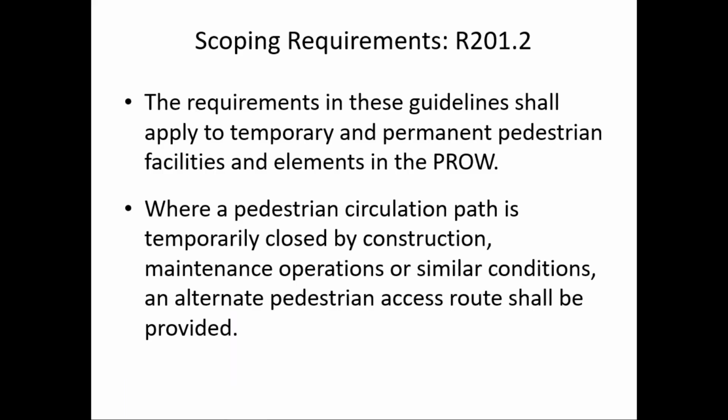Where a pedestrian circulation path is temporarily closed by construction, maintenance, operations, or similar conditions, an alternate pedestrian access route shall be provided. So there's that word shall again. So it's a requirement that when a sidewalk is temporarily closed by the various reasons mentioned here, or it could be landscaping or building maintenance or whatever it might be, there needs to be an alternate pedestrian access route.